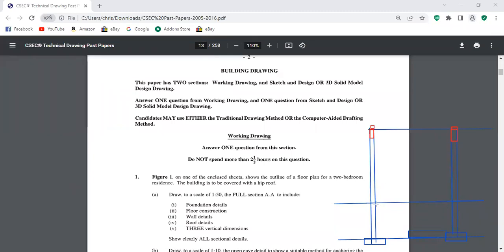We have the screed. So the screed will be the first level, right? Screed would be down here. Below the screed is what? The slab. And what's the dimension for the slab? The slab is 100. Screed is 25 to 50.